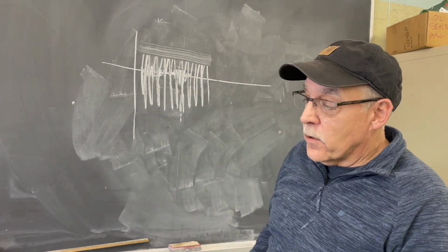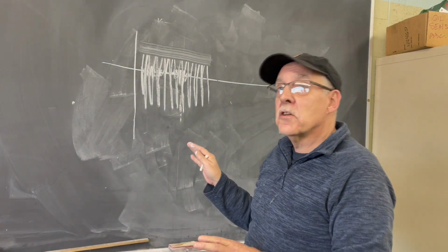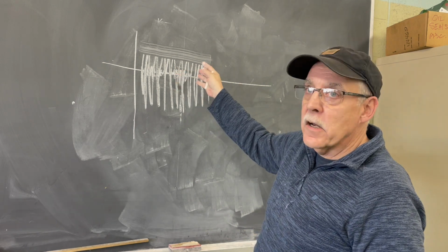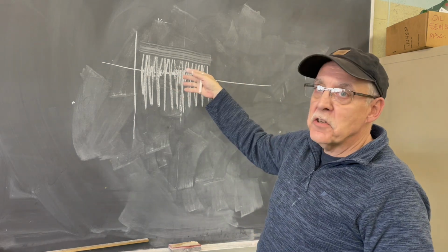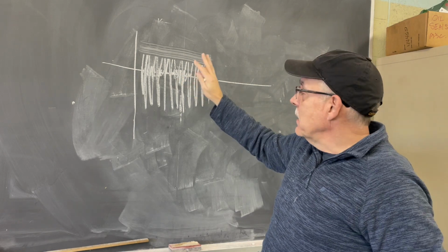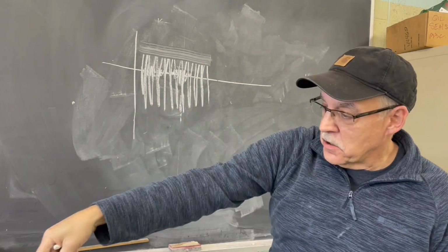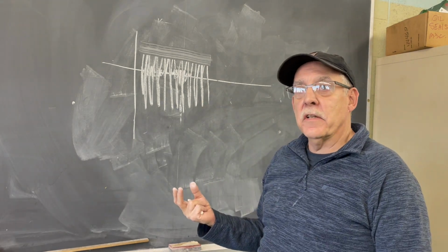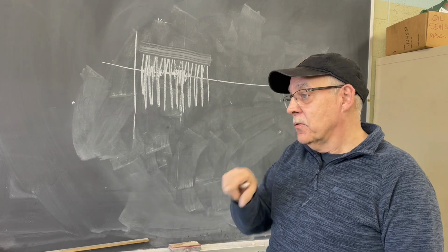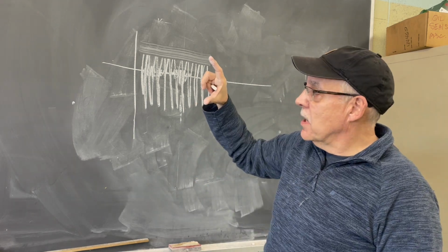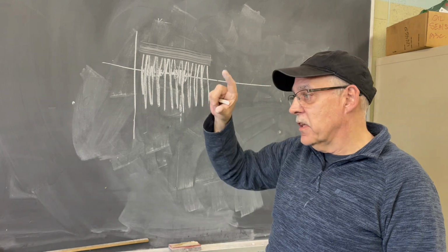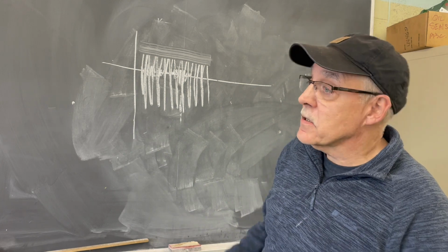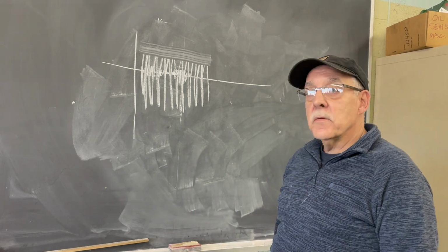So that complex waveform, just by looking at it, can tell you a lot of stuff about what's going on in that piece of equipment, okay? We take that complex waveform, we separate it out to look for individual frequencies, but just the pattern of the waveform alone can tell you broken gear tooth, inner race defect, modulation. We look at, okay, what causes it to modulate, right? As the fault goes through the load zone, more vibration, goes up, comes out of the load zone, less vibration. So we get this zzz, zzz, zzz, kind of, so you can tell different things by that. So it's all kinds of different things we can tell.